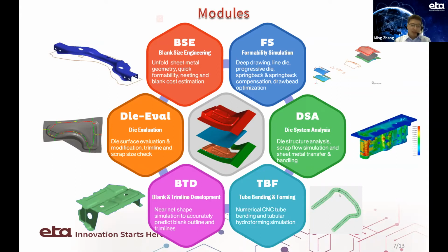Dynaform also has a Blank and Trim Line Development module, which conducts near net shape simulation and predicts the blank outline and trim line using an iterative optimization approach.